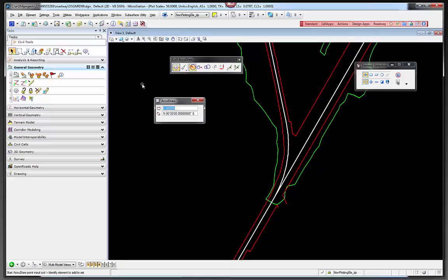function 8 key that will toggle on one versus the other. So notice that if I'm using the F8 key, and if I hit F8, notice how Civil AccuDraw activates and MicroStation AccuDraw deactivates. And if I toggle it again, now MicroStation AccuDraw is activated and Civil AccuDraw is deactivated. So there's a toggle out there with the F8 key that will allow you to do that.